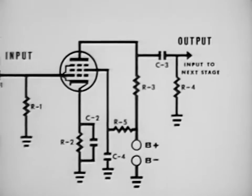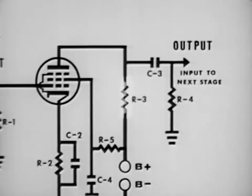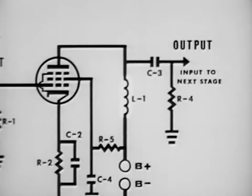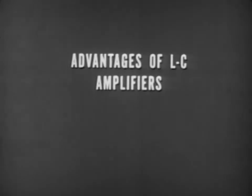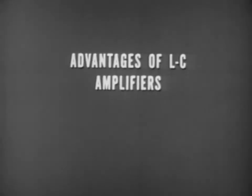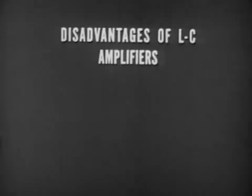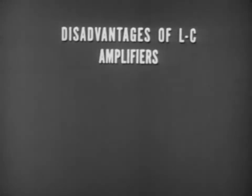Now let's change the plate load resistor to an inductor, and we have an impedance-coupled, or LC, amplifier. LC amplifiers have one particular advantage. Removal of the plate load resistor reduces the voltage required from the power supply. However, LC amplifiers have a disadvantage.